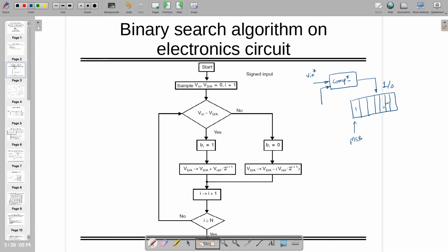There is always a shift register where the first code goes in with 1, others are 0, then this 1 is always getting shifted, right or left, whatever you like, right? And for a particular bit position, whether you need to keep it 1 or 0 will also be decided by this 1 and 0. Although the shift register will always be shifting till the last point, this 1 and 0 will tell whether a particular bit has to be 1 or 0, right?